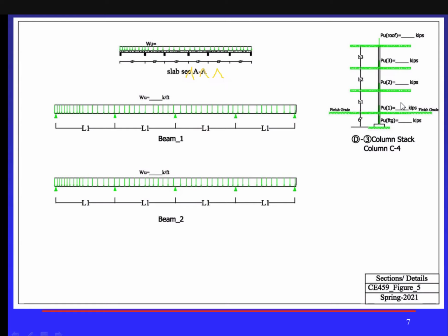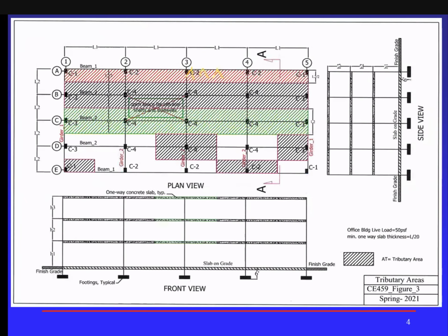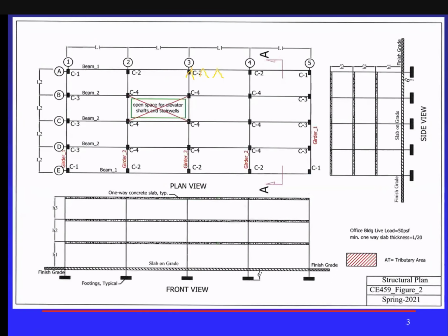So the only thing you're gonna come back to is the shear stirrups, which is not really a big deal for the beams. With that, then we're done designing the building for gravity loads. Okay, that means for gravity load, dead load, live load, our design is done. Oh, I'm sorry, with the exception of the footings. We have to design the footing later on after we get that.